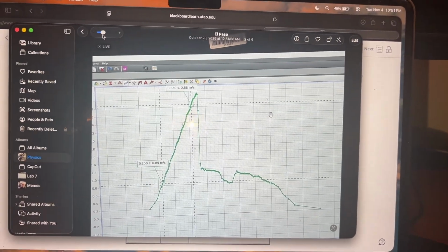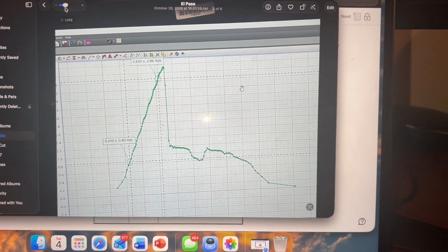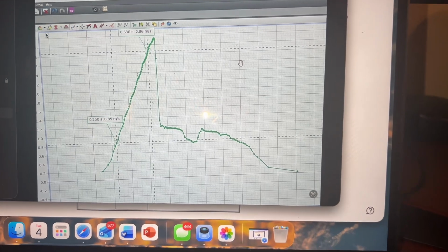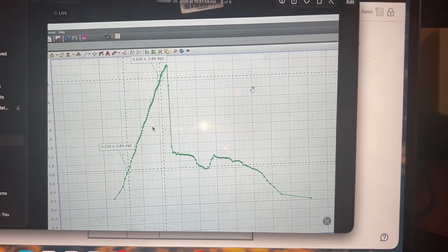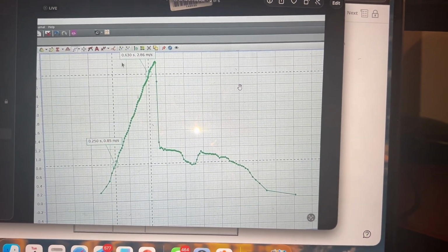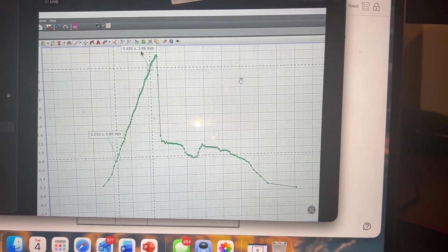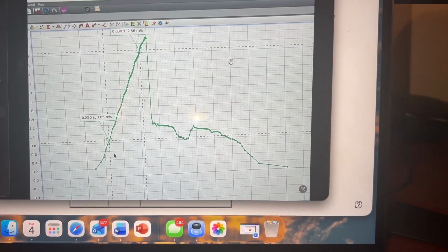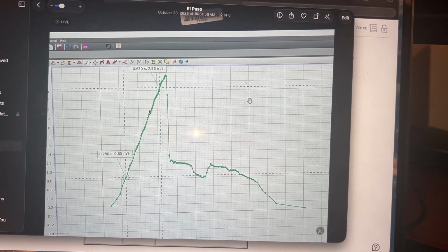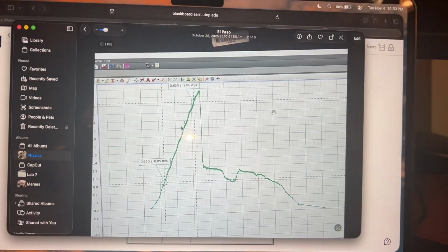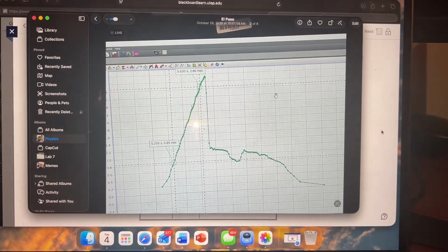Okay guys, so here's gonna be the graph for the experimental for the 2 pulley system. So here are our values right here. Same thing, we got the slope of the system when it recorded with the sensor. And then same thing, the delta V over delta T, we grabbed the velocity over time for both of these points, subtracted them minus each other, and then found those values. Okay, so then with this graph, we're gonna shift to our experimental acceleration here.